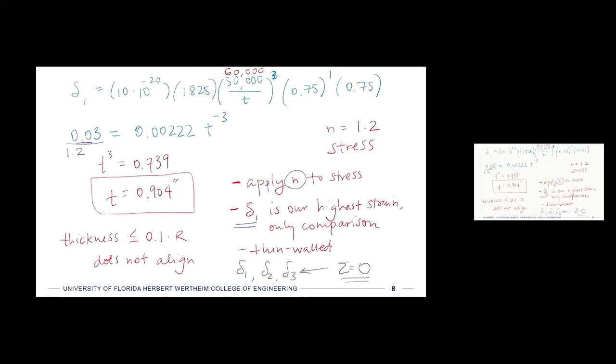And so if you do that, you will find that 2 out of the 3 of these will be non-zero, and you could use an effective strain, right? So you could calculate some effective strain that's a function of all of these 3 principal strains, and then use that compared to the maximum strain allowable, right? So then you'd have a combination of directions.